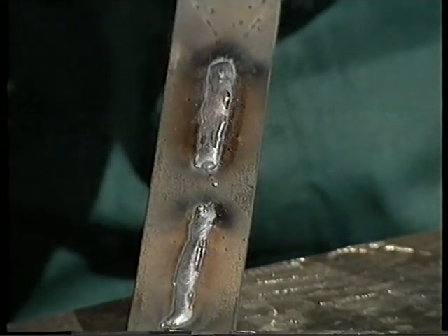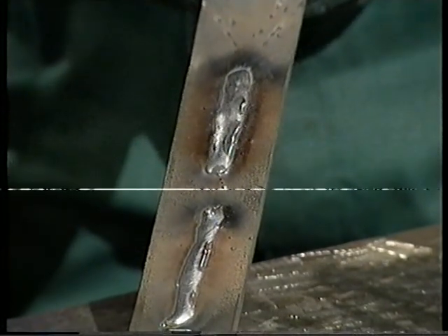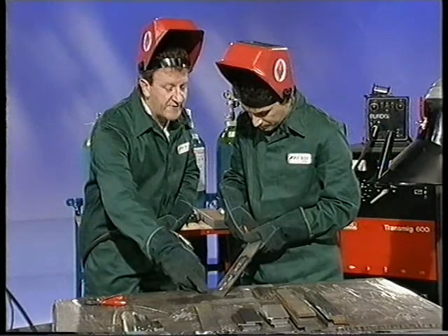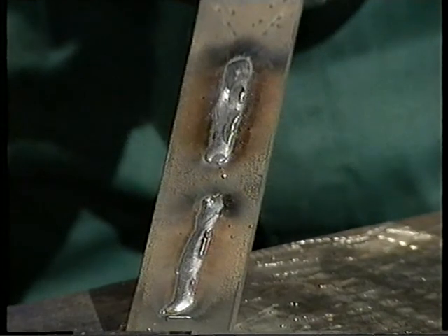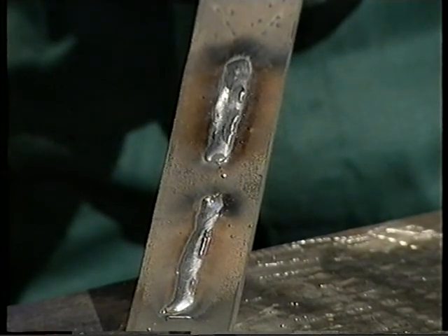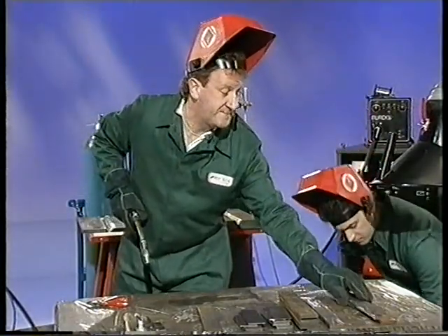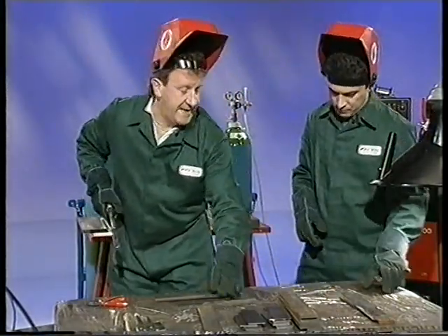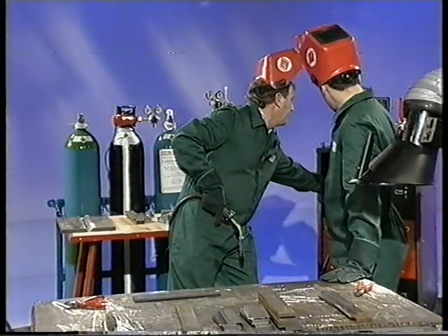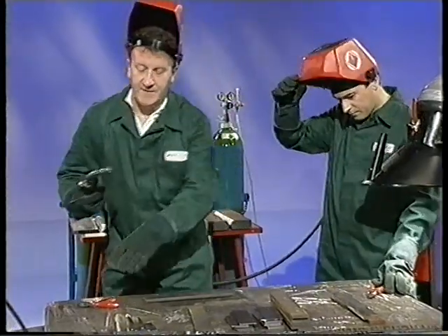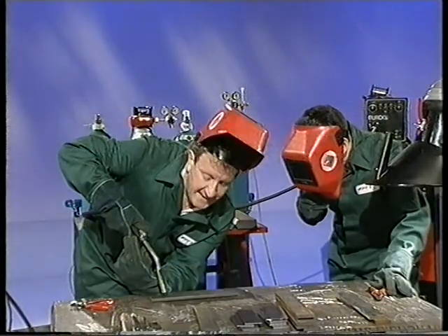You'll also have noticed that I used a longer stick out because it's higher amperage work, probably 18 to 20 millimeters. Because we haven't ground this plate, you can see silicates on the surface. This is an additive to the wire that helps mop up any impurities there may be. For very best effect, of course, we would do that on ground plate. And I will just trim that voltage back a little to reduce the arc length. Snip the end of the wire, and let's see what we have now. Mind your eyes.